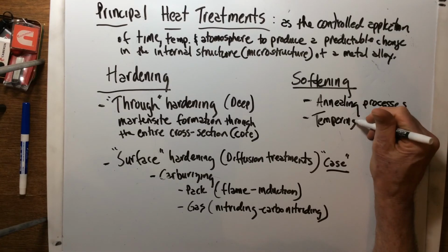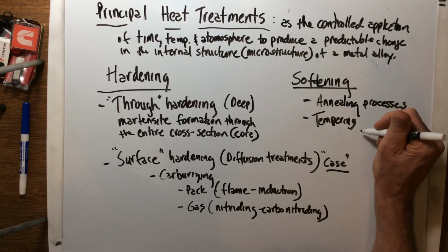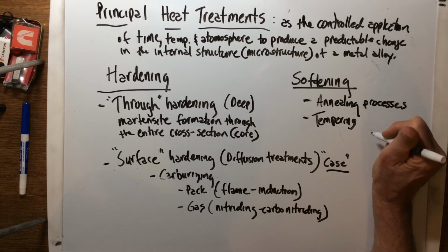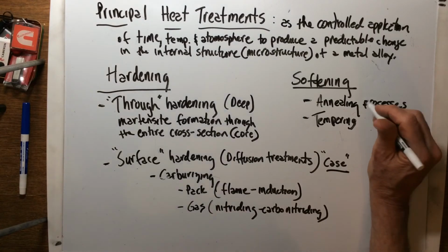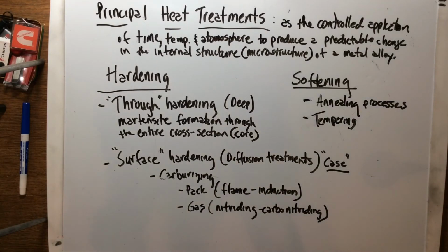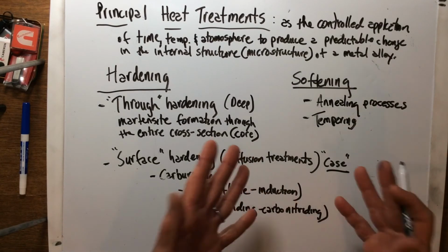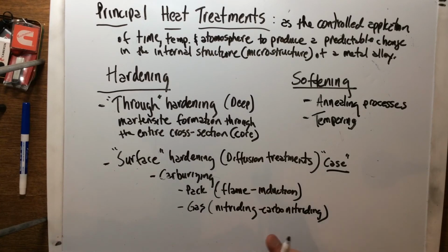All right, and that's where you just take and reintroduce that part after it's been quenched very quickly, and put it back in a furnace at about 350, 400 degrees or so, and go through that to soften it some and to bring back some of those properties that would enhance it as far as being usable.